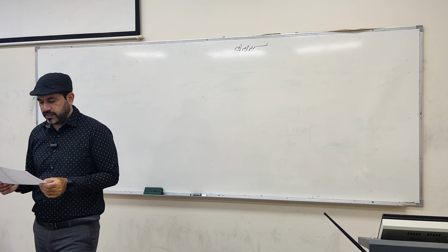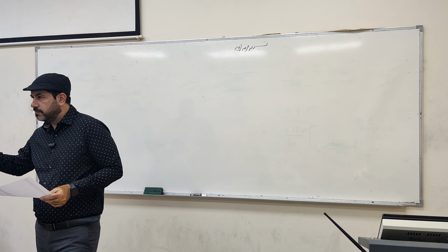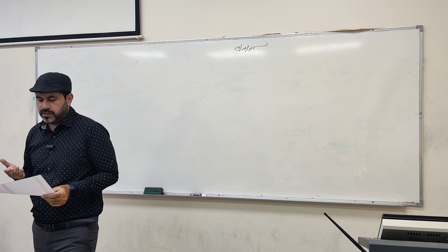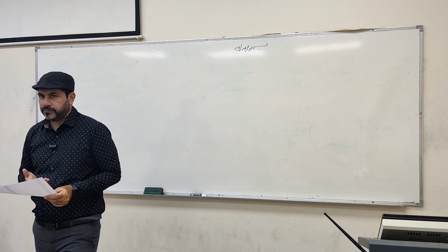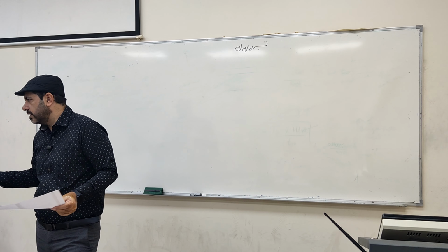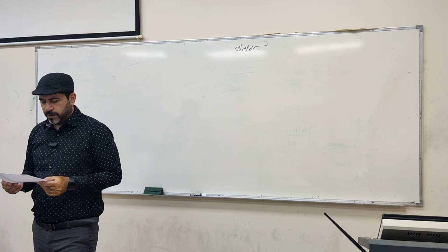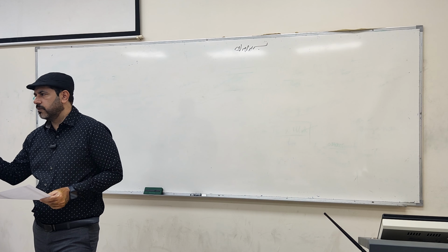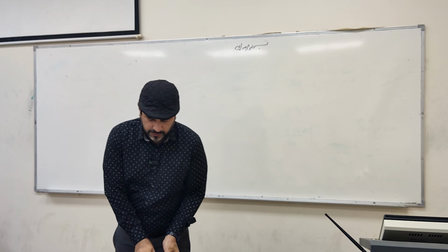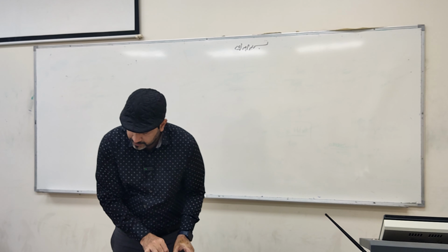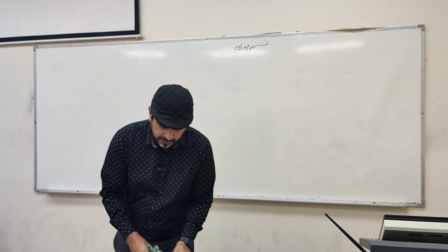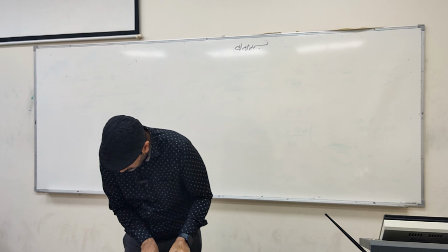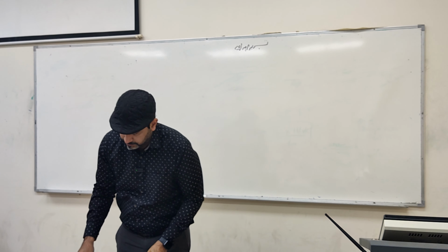So what we need to do is find the total area under the curve. This one is very simple, because this diagram is nothing but a combination of rectangles and triangles, and finding the area of a rectangle or triangle is very simple. Once we get the whole area, we divide it by the total revolution, and hopefully we get the T mean. Then the formulas which we used earlier we'll use to get the second part, the total fluctuation.